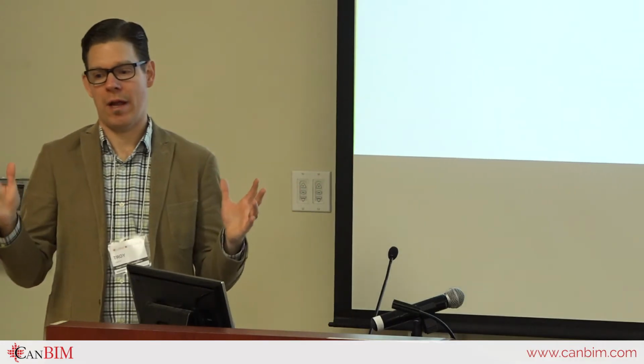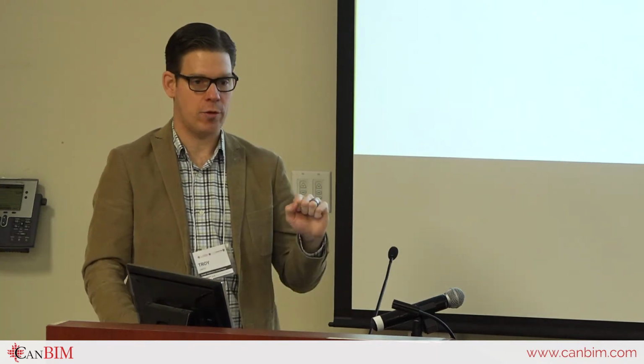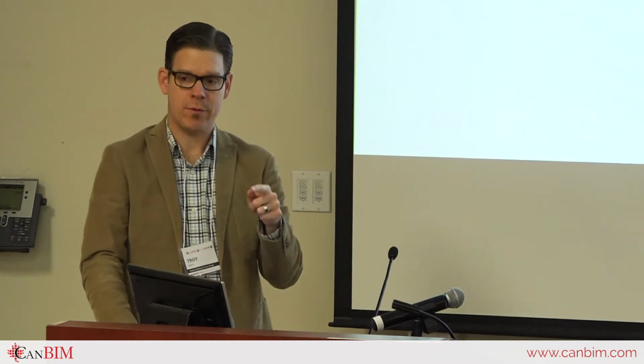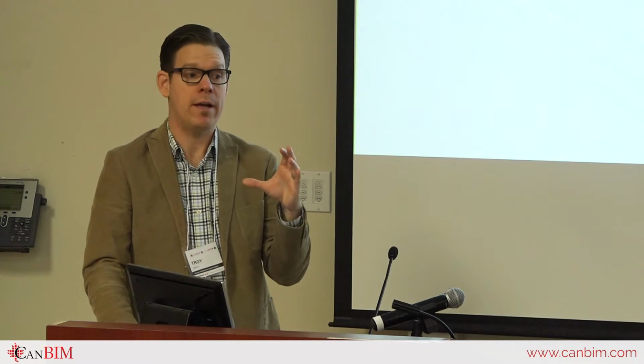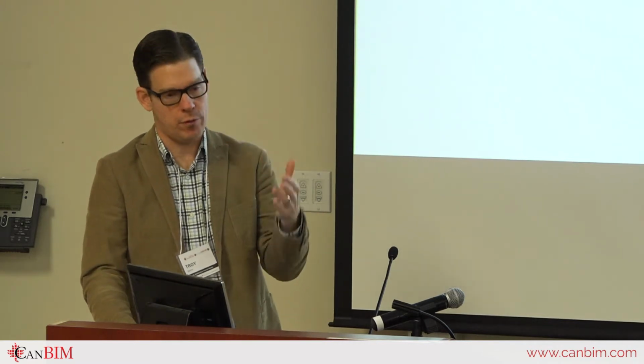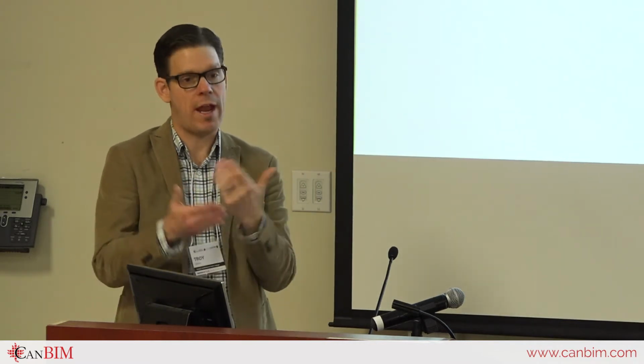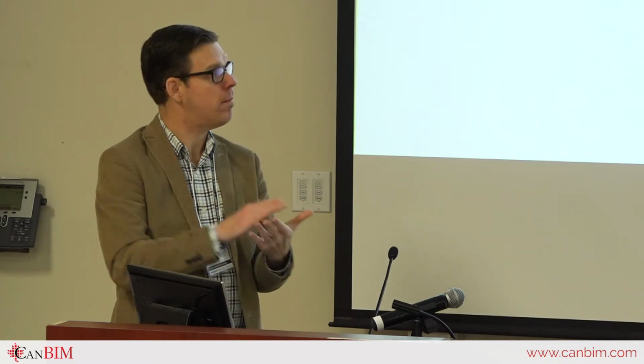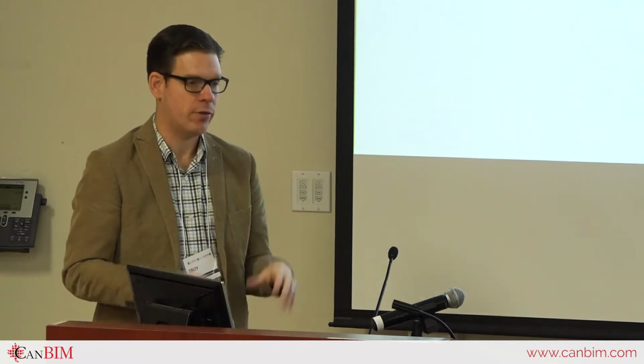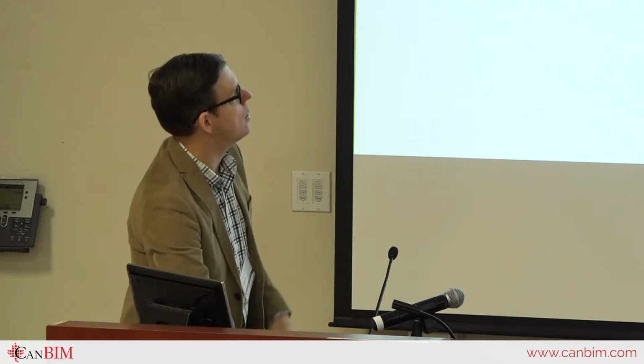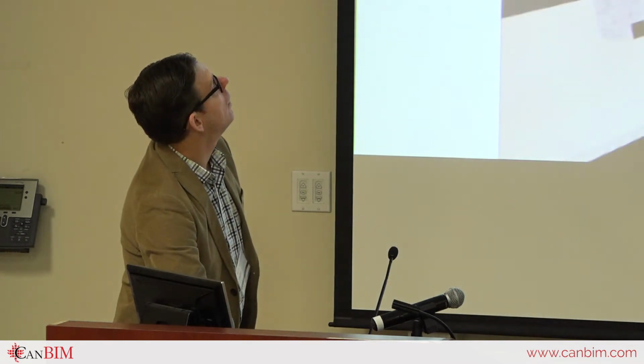And you can actually check, dRofus will actually let you check areas between things. So for example, you tell it, I want a classroom that's 75 square meters. That's what's in the functional program. You put a classroom in that's 70 square meters, it'll tell you that it's not right directly in Revit. You can do it through a color, it can show you the errors that you've made on all those pieces to make sure that they're tied directly together so that you're not hopefully overriding information.